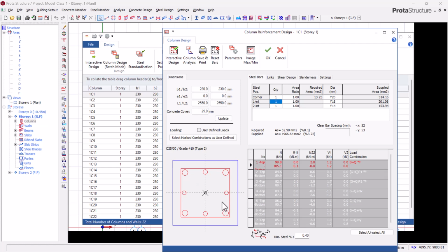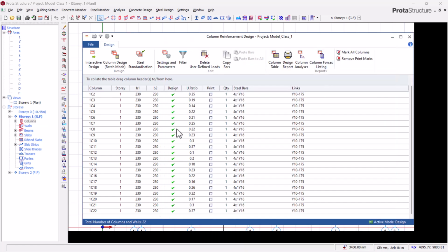if the reinforcement that was provided was not enough, you can go ahead and increase this number. You can even increase it to 2, but at the same time also consider your coarse aggregate size while you are working with this. So this is not needed. We don't need all this. Our previous reinforcement was okay, so I will just cancel. And that is it for the column design.